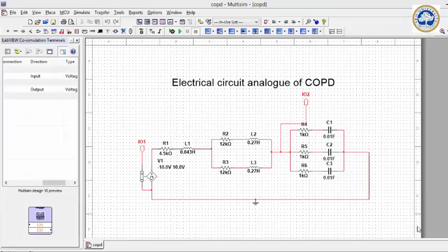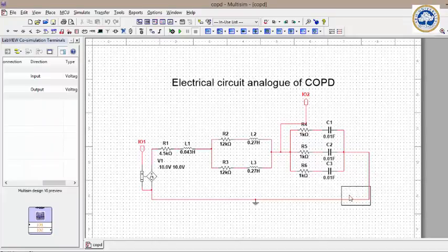Moving on to the real-time simulation. Shown on the screen is NI Multisim and LabVIEW co-simulation. After the construction of the circuit in NI Multisim, the circuit has been compressed to make it accessible to the user in the LabVIEW screen. Once the ports are connected, the LabVIEW co-simulation terminals can be renamed for the type of input component they represent and the direction of usage, whether as input or output.